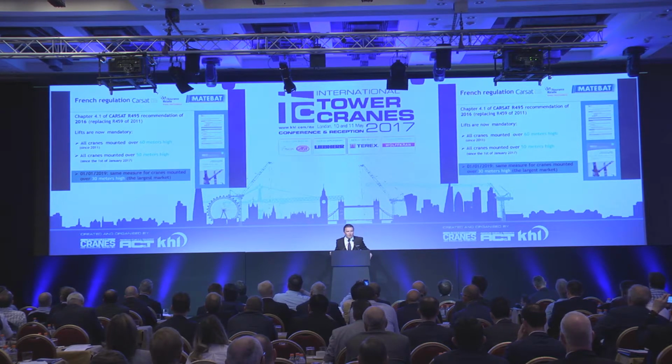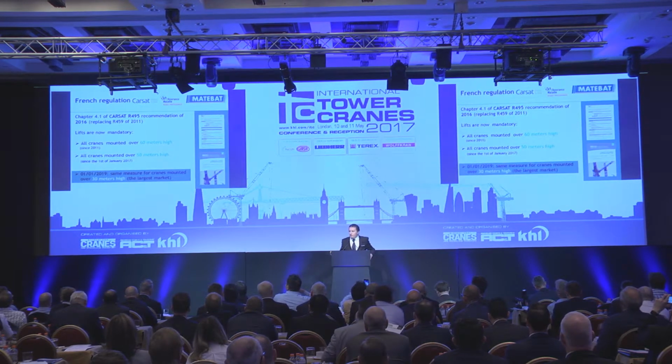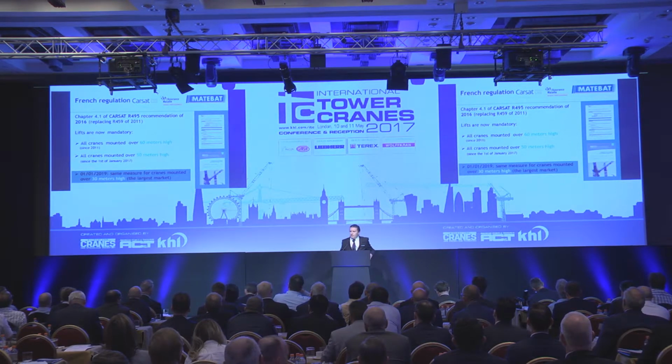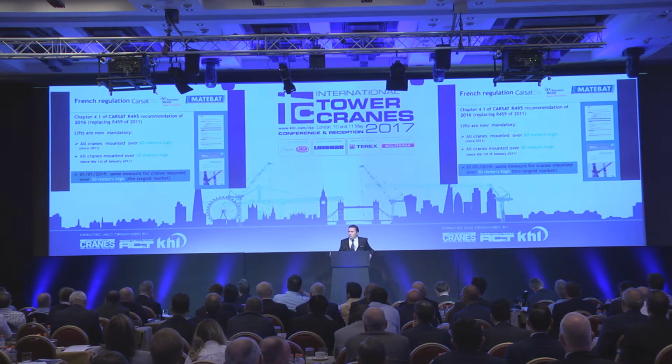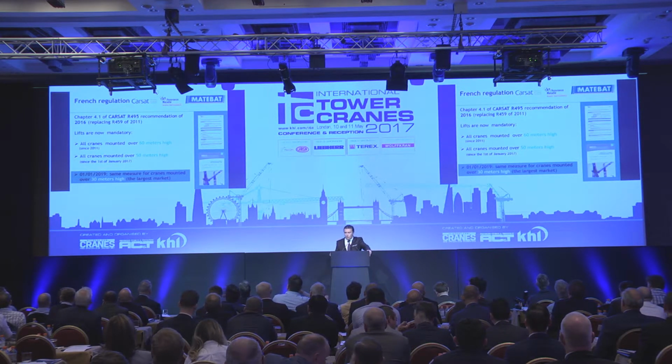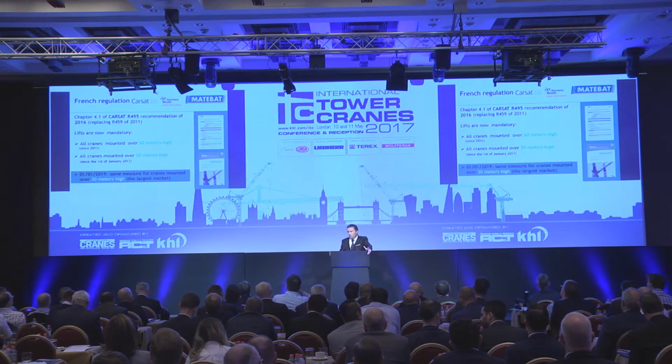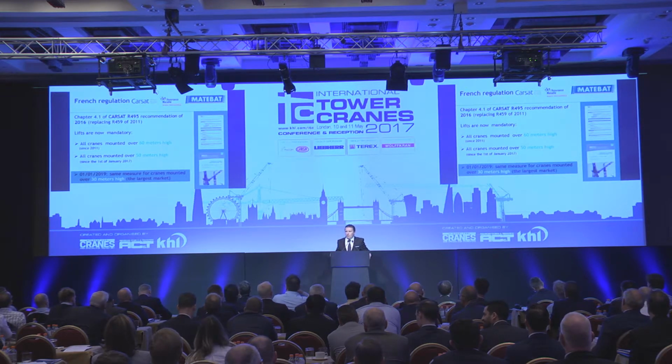It is becoming mandatory. It was already the case above 60 meters. It has now been a new involvement since the 1st of January this year. So now it's mandatory to provide the operator with a lift to erect the crane when it's above 50-meter elevation. And most importantly, it will become mandatory in 2 years for any crane above 30 meters.